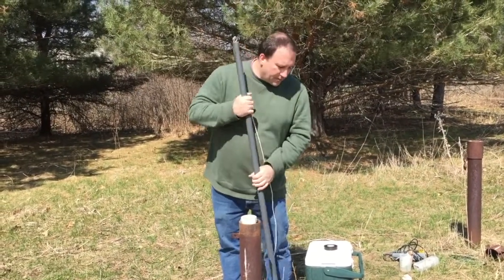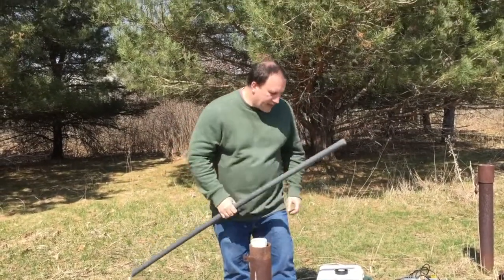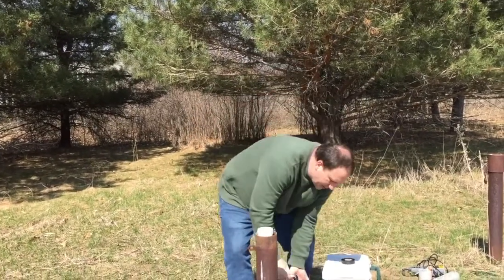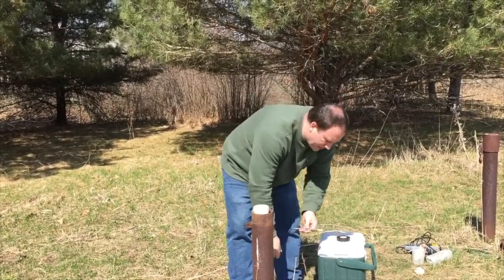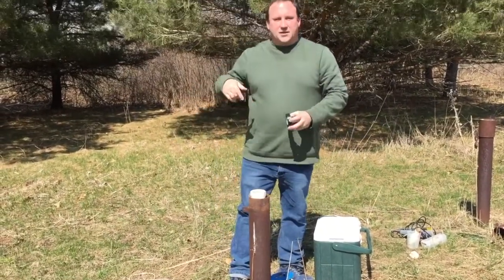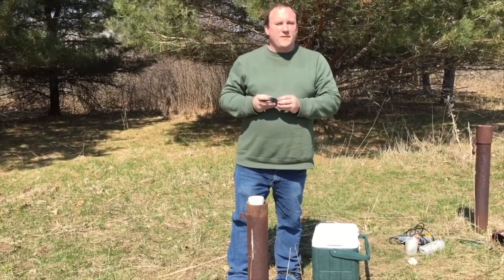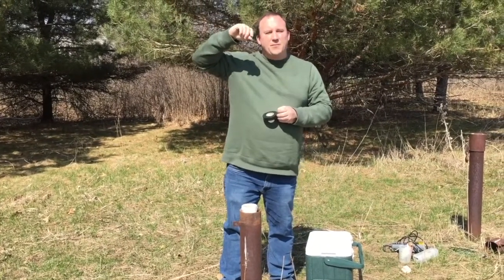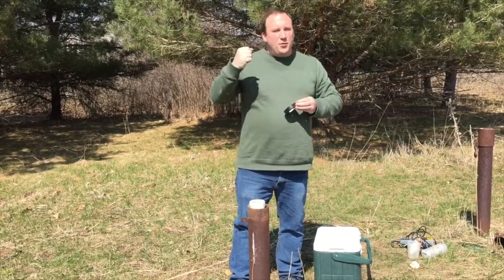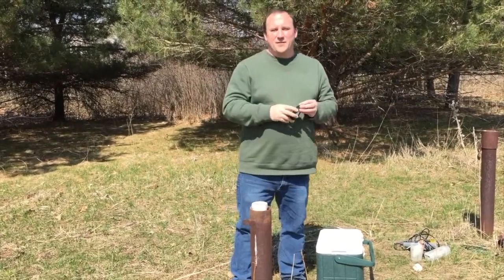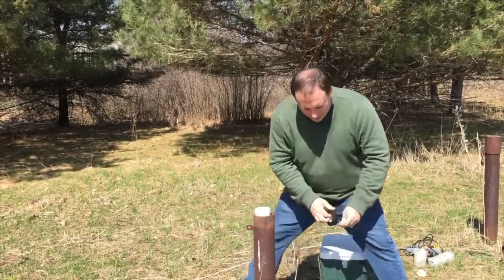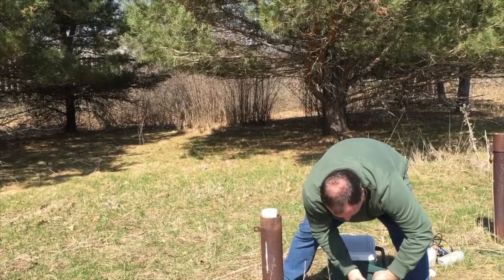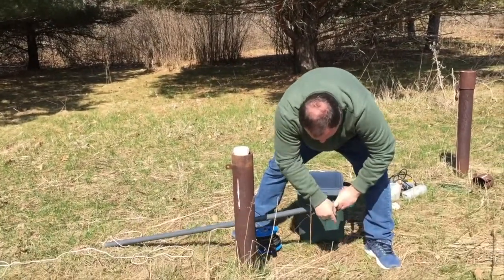But the first thing we need to do before we can do anything like that is we need to tape our water level indicator or some other kind of measuring device to the end of the slug so that I know exactly how far the slug is lowered. I know that it's 11.34 feet to water, so I want to have that at 11.2 feet or something hanging above the water before I do my test. If I put it in the water before I start my test, I'm going to get a funny reading. And so how we usually do this is just tape it on with some electrical tape, and it usually works pretty fine. It doesn't have to be pretty, it just has to be solid.